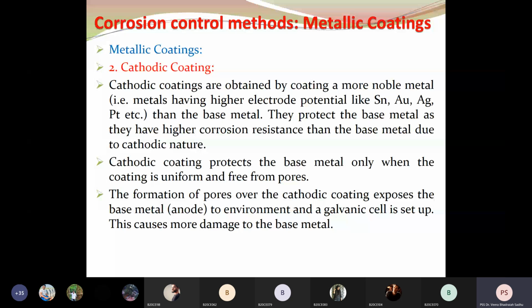So to avoid pores and cracks, you generally use noble metals. Noble metal films on the surface are generally very smooth, without any pores or cracks. So this film doesn't allow any chemicals to reach the base metal. So that means you can protect well.